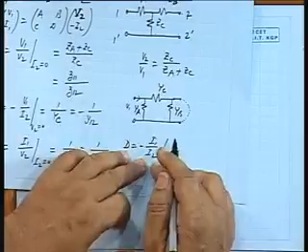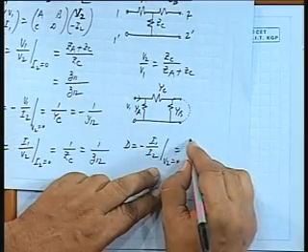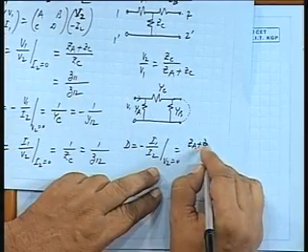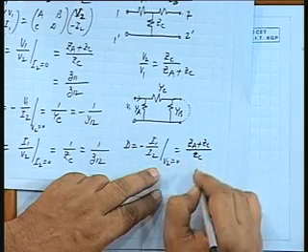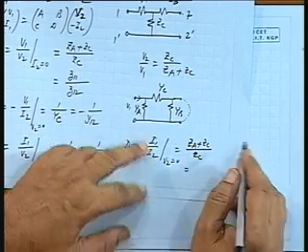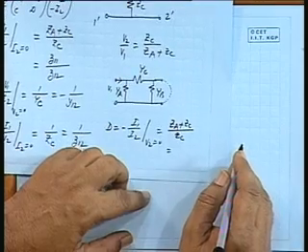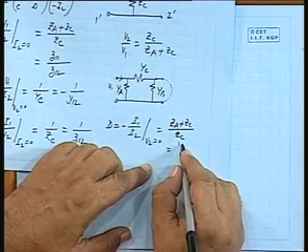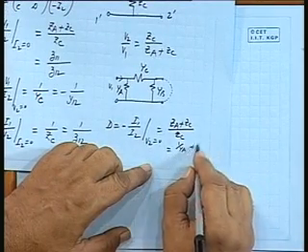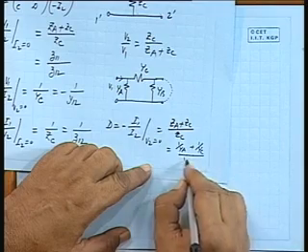If you talk in terms of impedance, say it is ZA by ZA plus ZC, is it not? So, I1 by I2, I1 is a higher current, so it will be ZA plus ZC by ZC, which means, with Z as 1 by Y, 1 by YA plus 1 by YC by 1 by YC.